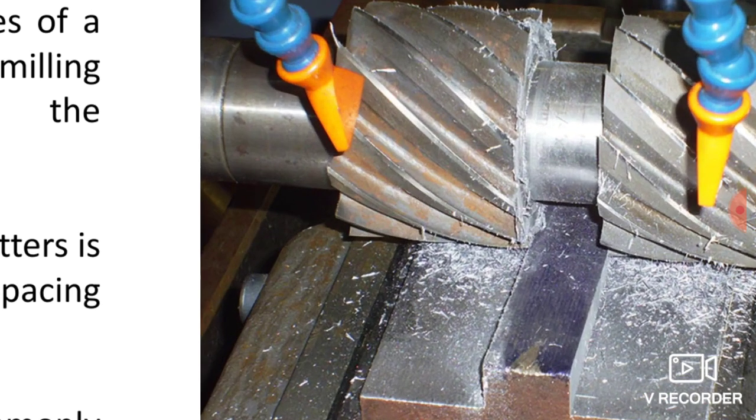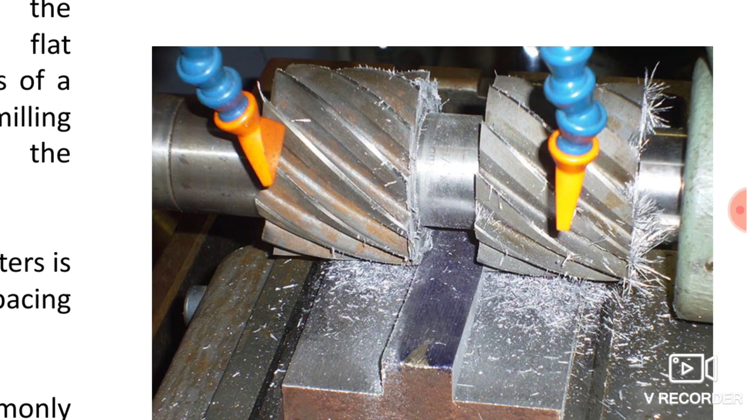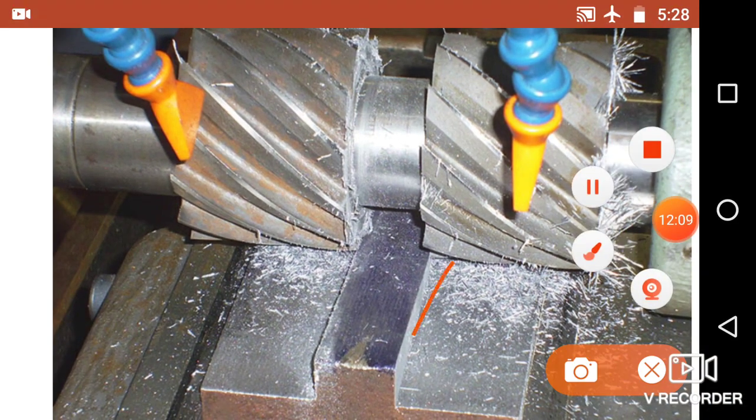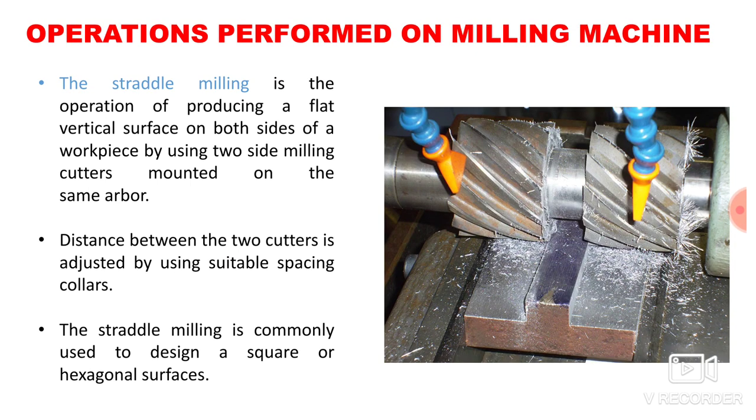So here you can see an image of straddle milling. On the arbor you can see two different cutters. The distance between the cutters can be changed with the help of a collar. Here these two different cutters are removing the material from the side. You can see this is nothing but the side of this workpiece. These are two different sides of the workpiece, and the material is removed with the help of these two different milling cutters. This is known as straddle milling.